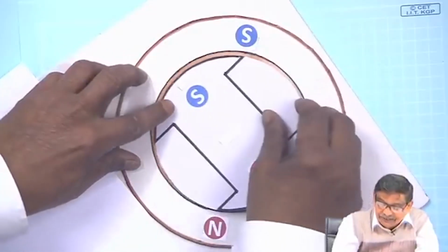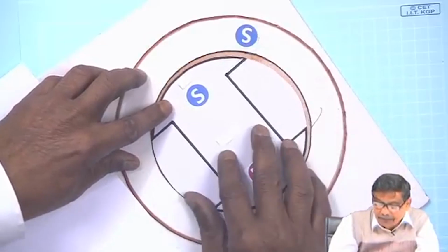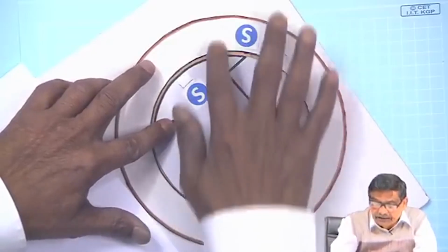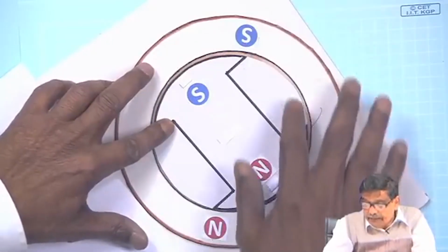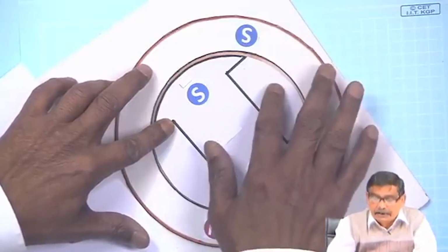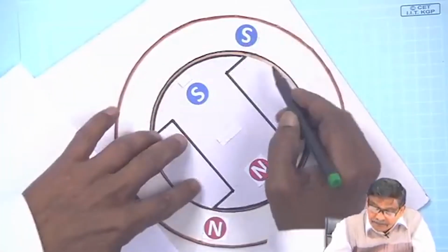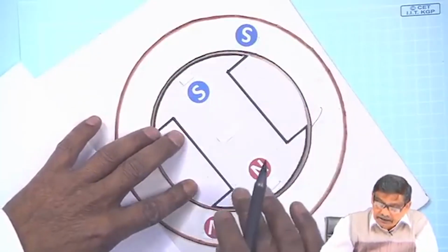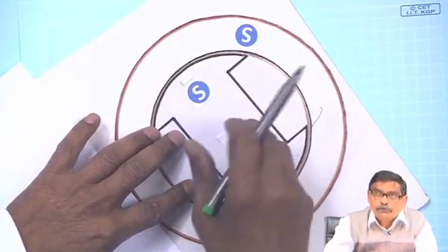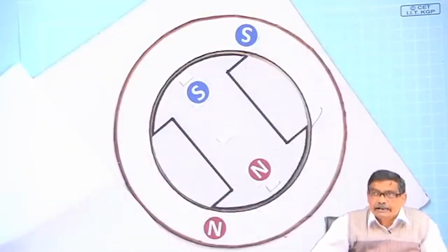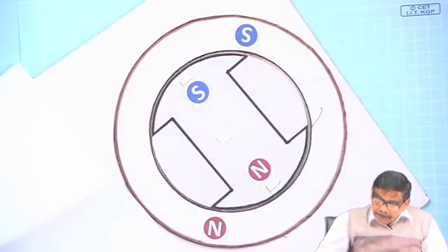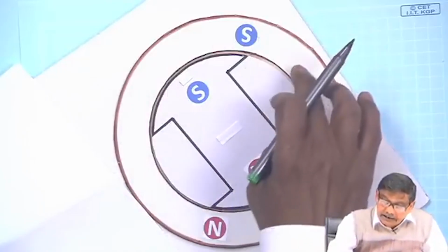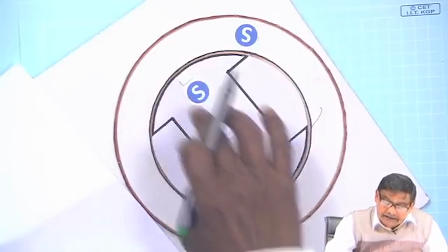So, suppose it is at an arbitrary position. You also notice this part can rotate, this part is stator. There must be some air gap in between, that is this portion. A uniform air gap will exist in any rotating machine, so that the rotor can freely move, it should not strike the stator iron parts. So, for smooth rotation there must be some air gap, you cannot avoid that. So, a stator, rotor and this one.